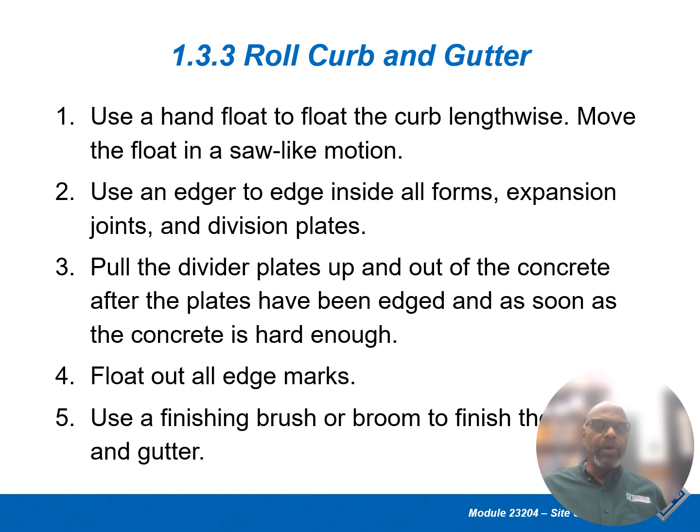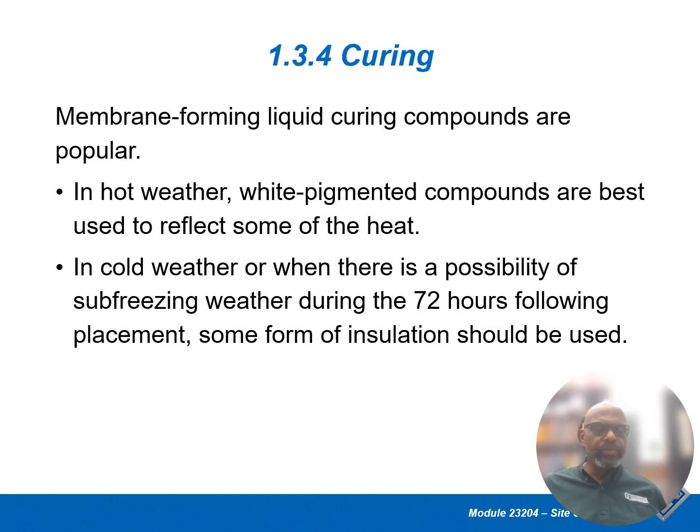Float out all edge marks. Then use a finish brush or a broom to finish off the gutter and put that surface on it. That is really important when you are using a broom to put that finish on.